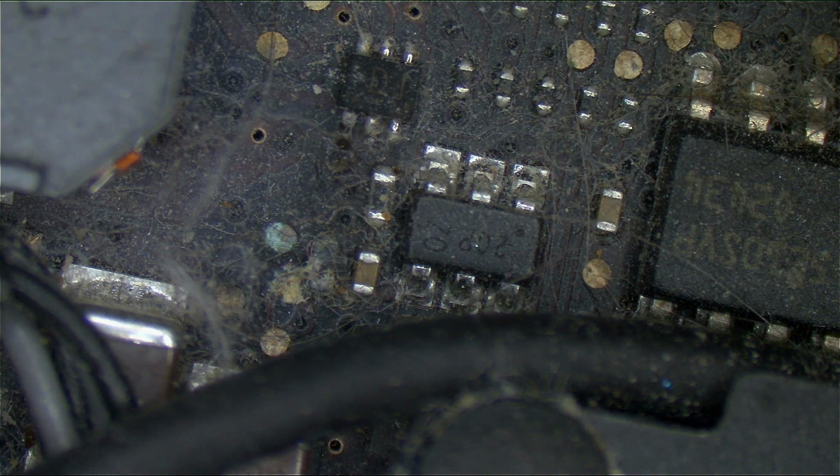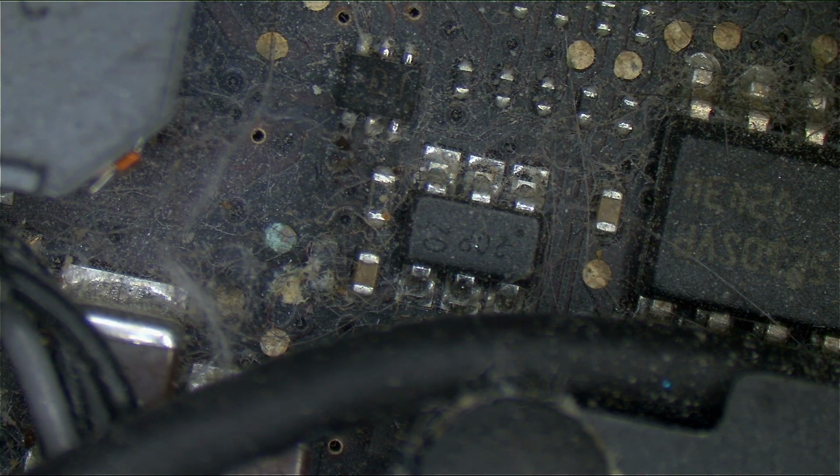Now we have a couple of different possibilities over here. The first possibility is that this resistor is blown, this resistor is dead, so it's not going to do any voltage dividing. The second is that this set of transistors are dead, so they're not going to send it to ground, they're not doing their job. The third possibility is that this transistor over here could actually have a short between pin 4 and pin 3, so it's constantly sending all of it, so it's bypassing this resistor. Instead of sending a little bit over here, it's sending all of it over here.